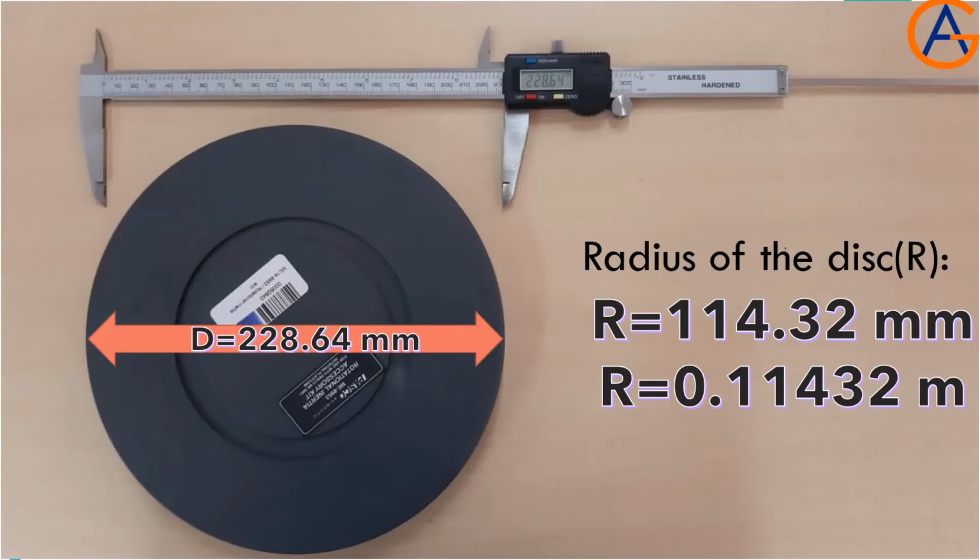Now let's measure the radius of the disk. We have measured the diameter of the disk with the digital vernier calipers. It is showing 228.64 millimeters. This is the diameter. Divide this number by 2 to get the radius in millimeters, then divide by 1000 to get the answer in meters. So the radius of the disk, capital R, equals 0.11432 meters. This is constant in this experiment.